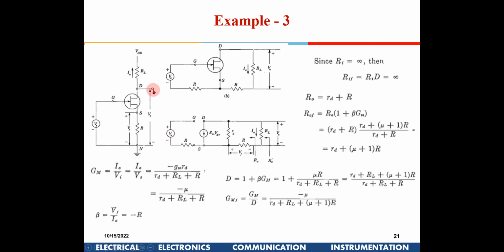We are not sampling voltage. See, the output voltage is here, not here. So your feedback depends on the current which comes to the R, right? Now, depending on what load is connected here, the current which is flowing here develops a voltage here. So now it is current and voltage out here, right?